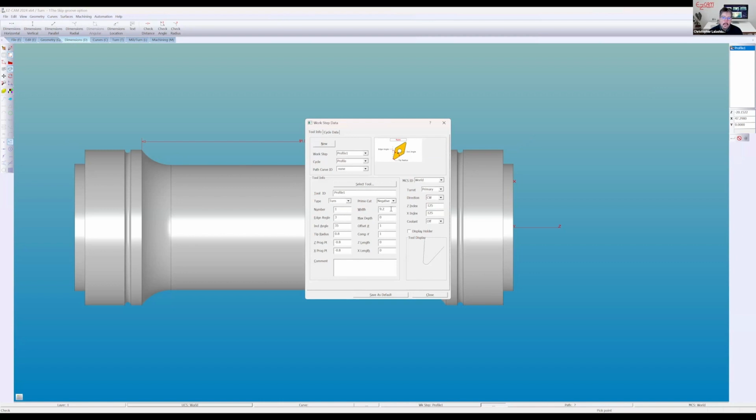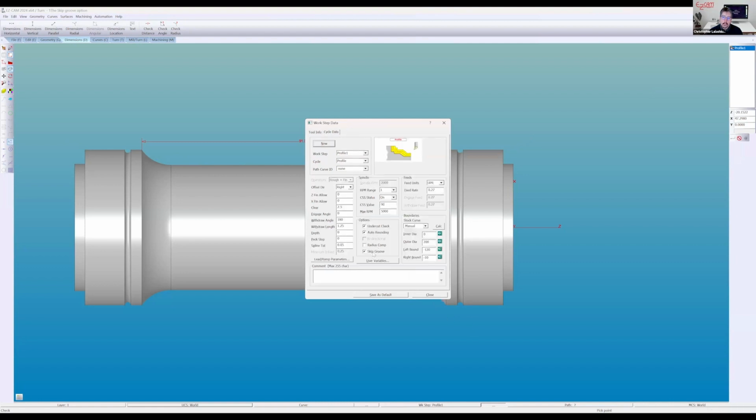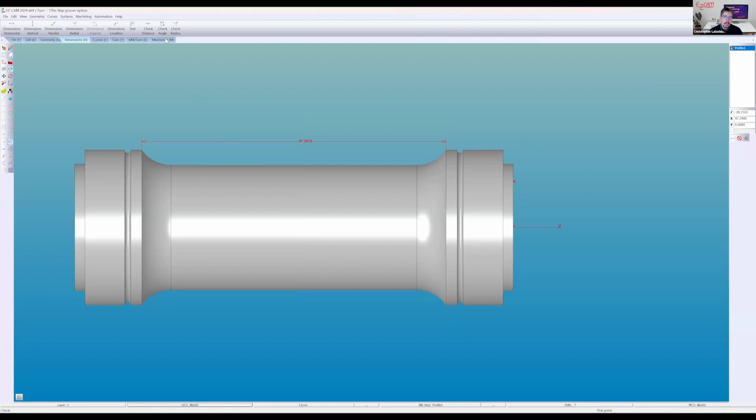Now the width is strictly for skipping over grooves. It is not the width of your insert. So why might we skip grooves? Well, if you look at the insert, EZCAM wants to feed into any space that will allow the insert geometry. This may cause chatter or even groove tool deflection. And we do have skip groove checked. Verify our machining again, and we're good to go.